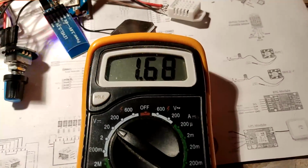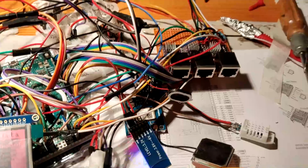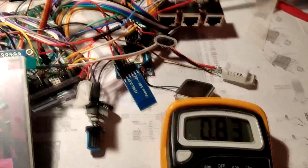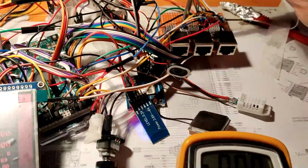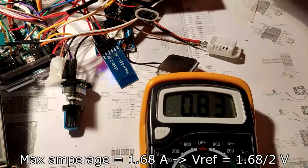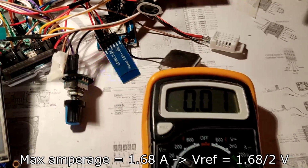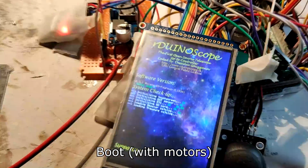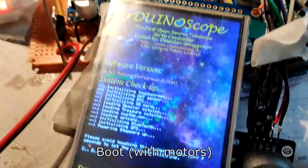Here we have the default Vref value, which is equal to the max amperage by coil. So I'm gonna adjust it to about half of this value, so 0.84 volts. I mention here there is no confusion between amperage and voltage. This is the weird procedure for adjusting these drivers. And now I'll let you see the boot of the rDUINOScope with the motors plugged.